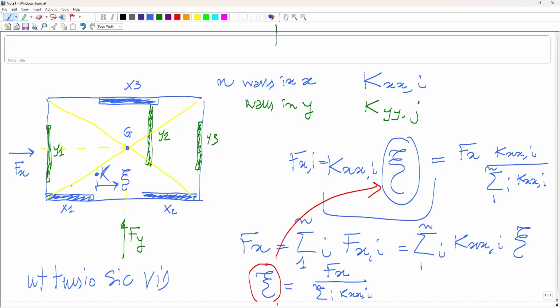But we are continuing to say concrete cracks. Reinforced concrete is a material where we do want to exploit the nonlinear behavior of the material. But most of all, when concrete cracks, you already are into some kind of non-perfectly linear elastic behavior.